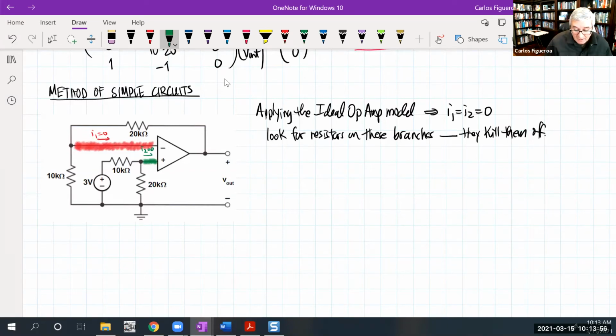So then I've got to start following the nodes here. Check this out. If I know that this is 3 volts right here, the thing you want to see is that I'm focusing now on V2. Look at what's special about V2. There's current coming from the power supply, the 3 volt source. So it's going this way, and no current's going into that branch, so it's coming down.